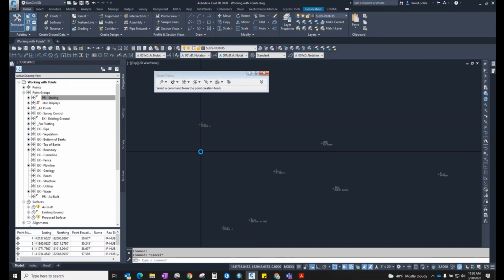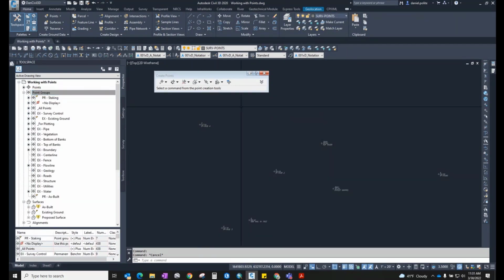I mean, the map's there, and you can say, oh man, I'm way off. It's not even showing in the right location. So it's always nice to have those points in there, even during construction checks. If you have those points in there, it takes 5-10 minutes to set up a total station, and you have that in your data collector and you just want to do a quick construction check, it tells you, hey, what's the cut fill? Is this contractor on or off? And you can let them know right away what needs to be done. So that's basically putting the points in your design.